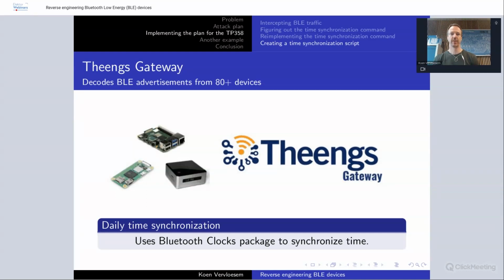Most of them are sensor devices. They're broadcasting their data around, and the Theengs Gateway project supports the broadcasting format of more than 80 devices. It picks up these advertisements, decodes them, and writes the decoded data to an MQTT broker. And then you can integrate it in your own home automation system, for example, to use this sensor measurement.